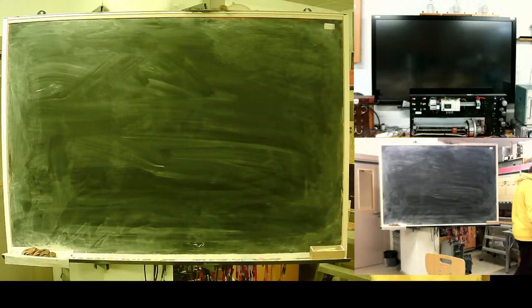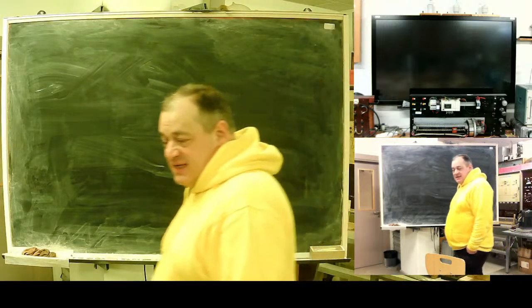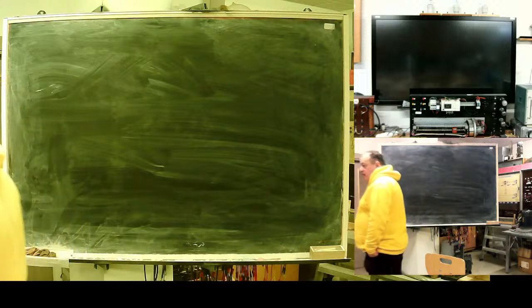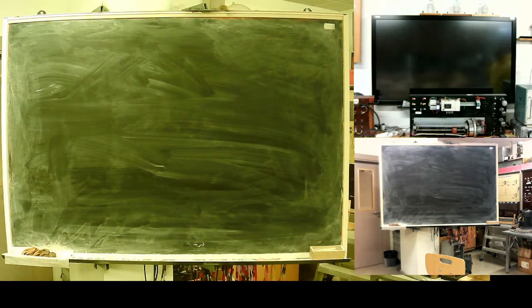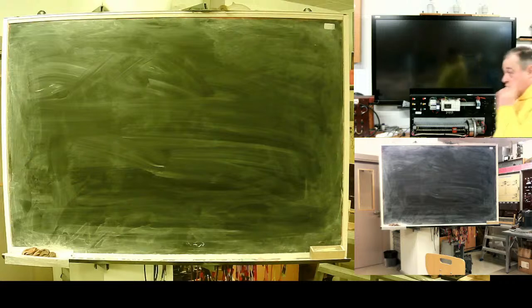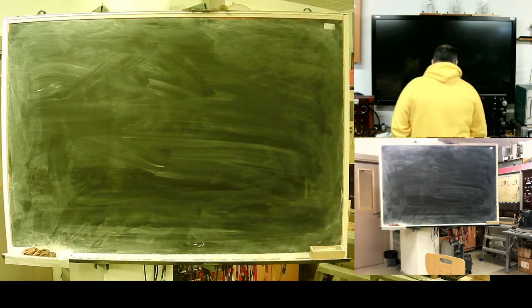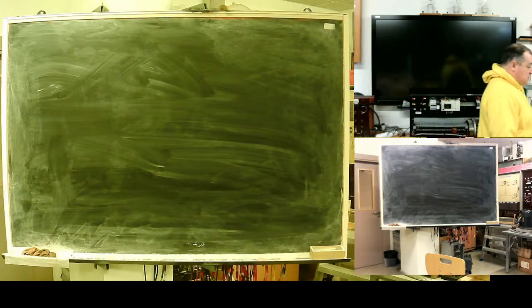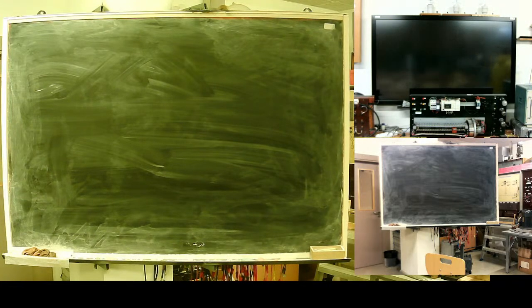Also, we need to give some time for the switch to cool down. Our circuit breaker can be operated virtually instantly, in parts of seconds. Some older designs need time to cool down. So we cannot switch back in a time shorter than the time required for the switch chambers to cool down.